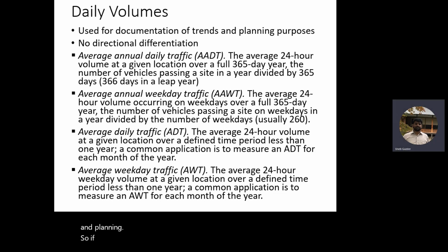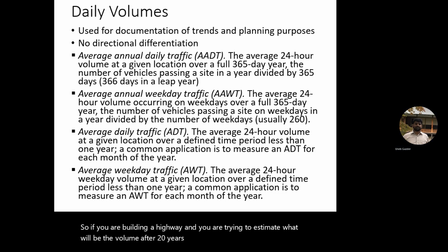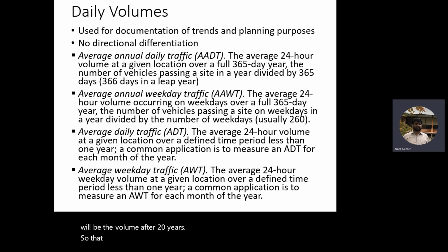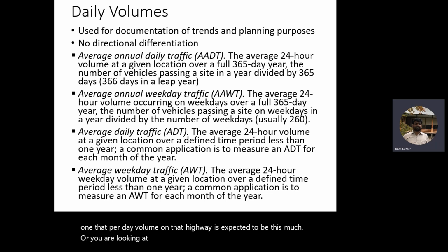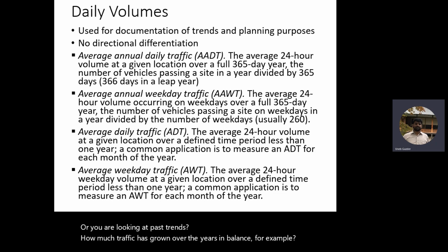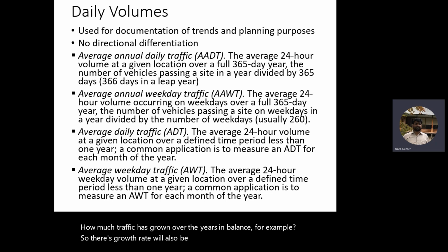So if you are building a highway and you are trying to estimate what will be the volume after 20 years, so the engineer or the consultant will give you a value of daily volume. That per day volume on that highway is expected to be this much. Or you are looking at past trends. How much traffic has grown over the years in Bahrain, for example. So this growth rate will also be calculated for daily volume.